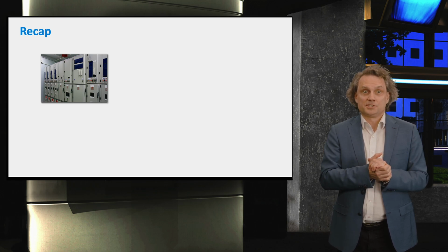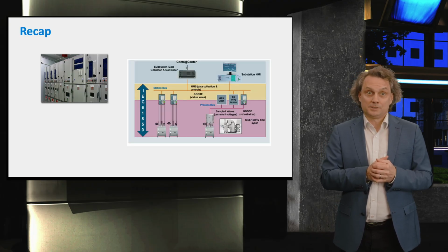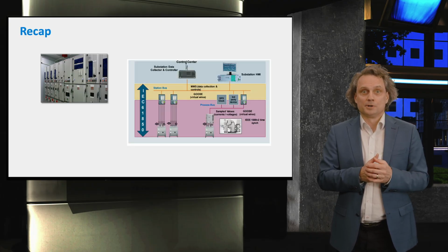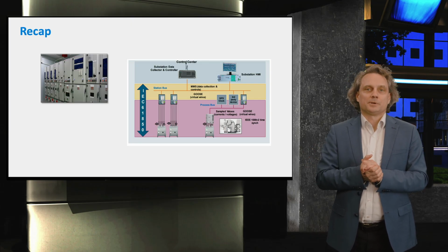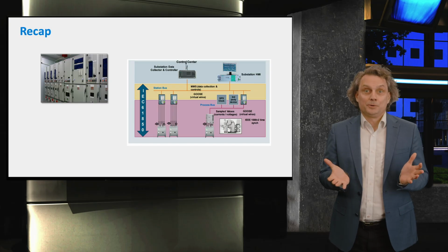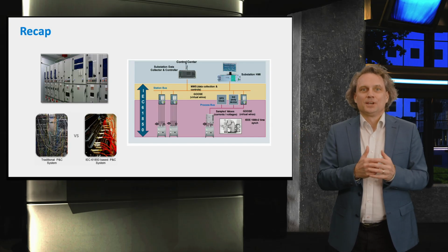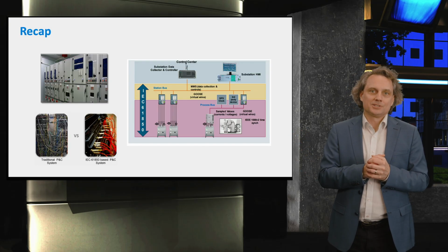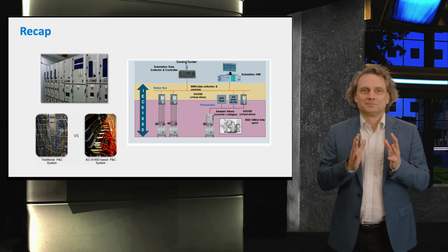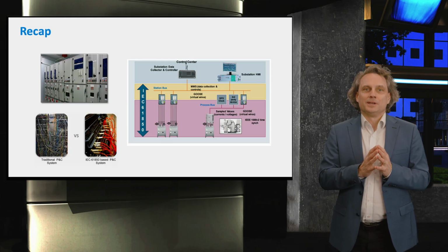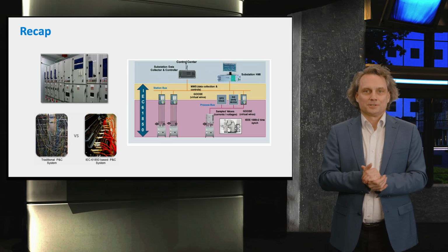IEC 61850 is a powerful standard with many subchapters. Core of it is a set of protocols. Some have real-time capabilities, such as GOOSE. Others are more semantically rich, non-real-time protocols, such as MMS. What does it help with? It improves physical OT topologies inside the substation, and it makes it easier to commission, to diagnose, and to make multi-vendor installations possible.